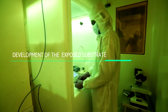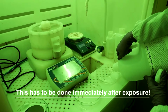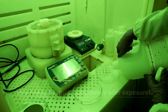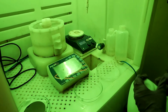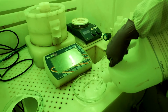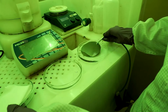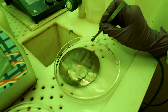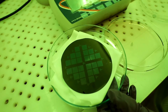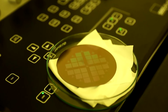Development of the exposed substrate. This has to be done immediately after exposure. In a clean beaker, take the required amount of developer, that is enough to submerge the substrate. Take DI water in another beaker. Dip the substrate for around 25 to 30 seconds. Now take out the substrate and immediately rinse in DI water beaker. Dry it gently using an air gun.